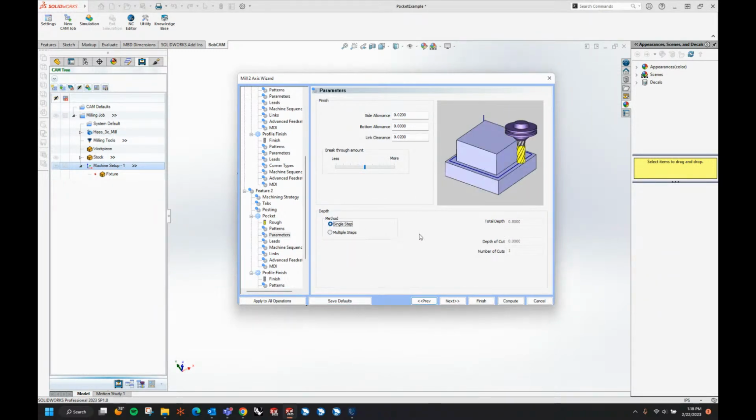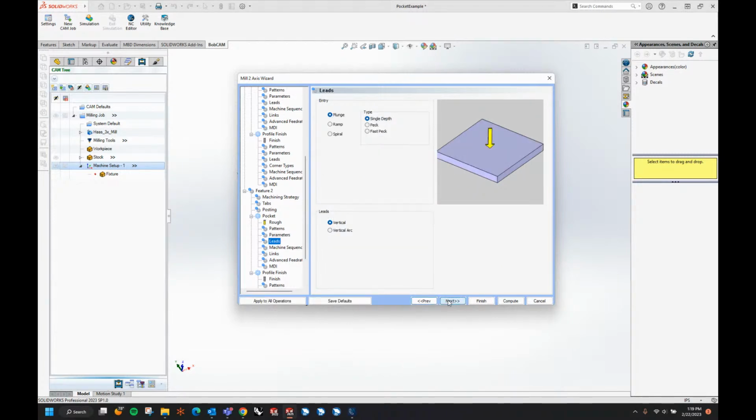The adaptive, when you're doing the radial chip thinning, which we have a white paper on our site, which I'll pull that up here in a minute if any of you want to download that to read more about the radial and axial chip thinning and how that applies and the formulas and all that good stuff. We have a lot of information for that, but this is technically made for a full flute engagement, full depth, but a very small step over. So we do want a spiral. We'll do about half, and I'll leave this one, we'll do about 7 degrees as well.